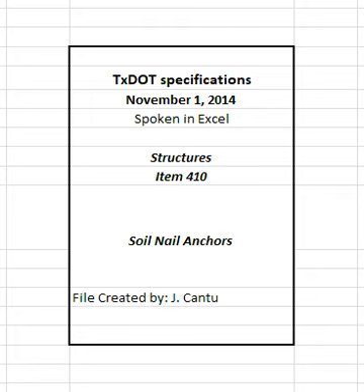Modify construction methods or procedures if the test soil nail anchors fail to provide the minimum pull-out capacity specified on the plans. Install and test additional soil nail test anchors until adequate pull-out capacity is achieved. Test soil nail anchors, in addition to the number specified on the plans, are subsidiary to this item.